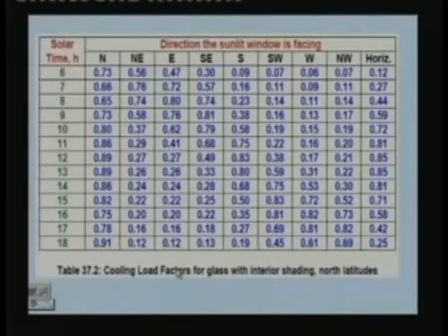This kind of tables are available in several handbooks such as the ASHRAE handbooks, for different conditions. For example, this is with interior shading. Without interior shading, you will have different values of cooling load factor for glass.